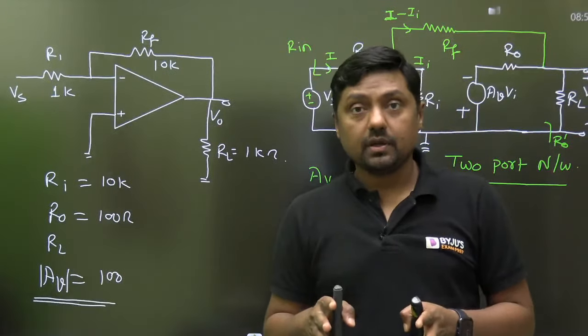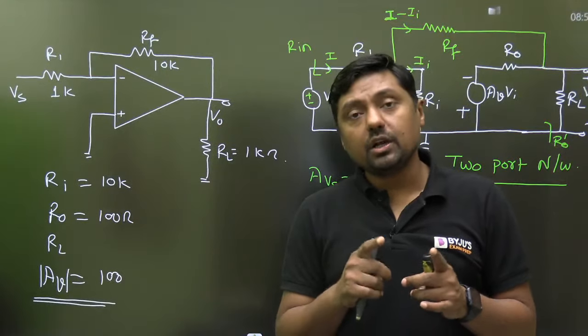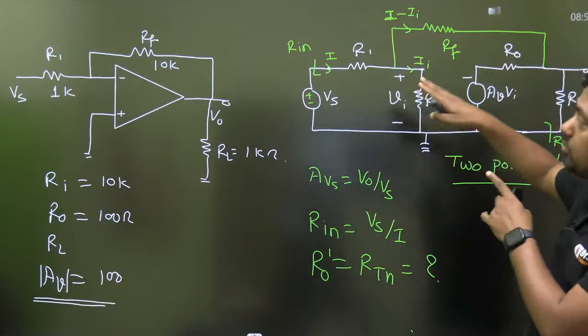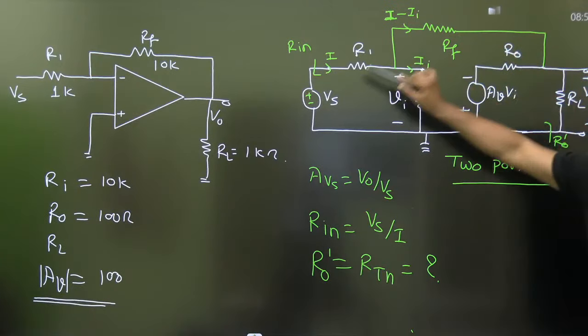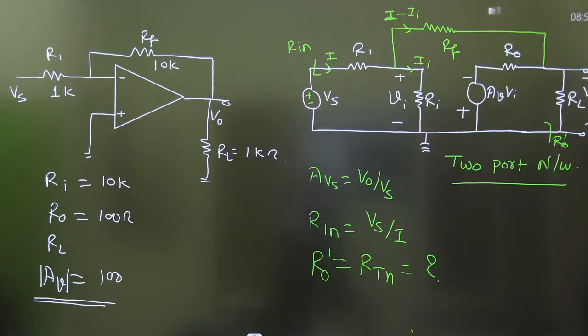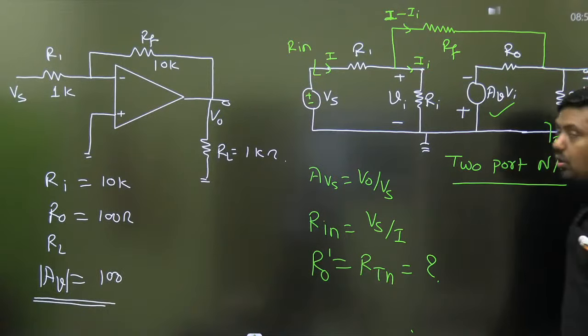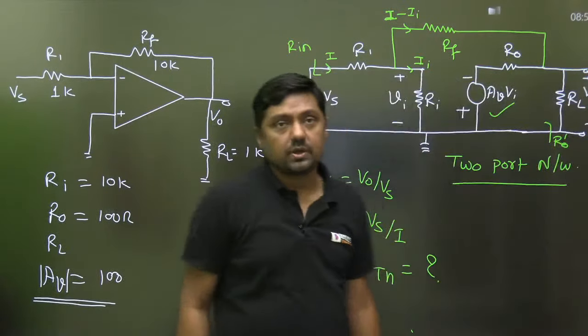Post your doubts also, right. Already one student has given me a doubt related to that particular question: why we are not connecting it in parallel, what is the virtual short concept. One student asked, sir, please draw the equivalent diagram related to R0. So that is the equivalent diagram, very simple, we can use. Normally students make a mistake here, they are not considering the 180-degree phase shift, and that's why they get the wrong answer for this particular question.